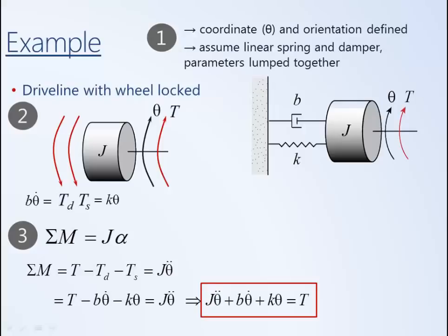Again, since this is sort of a passive system, we would expect all of the coefficients of like terms to have the same sign, indicating that the roots of the characteristic equation have negative real part, meaning we have exponential decay, not exponential growth. Since the signs are consistent, that gives us some indication that we did this correctly.